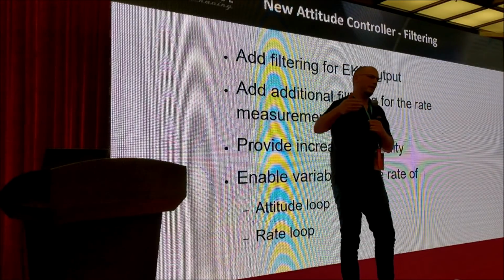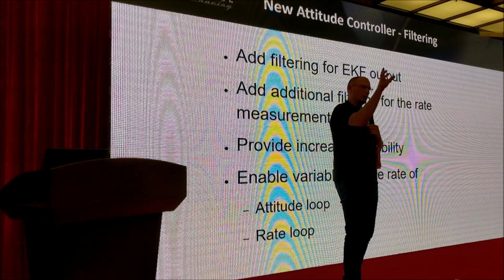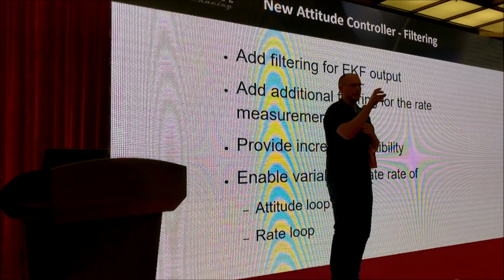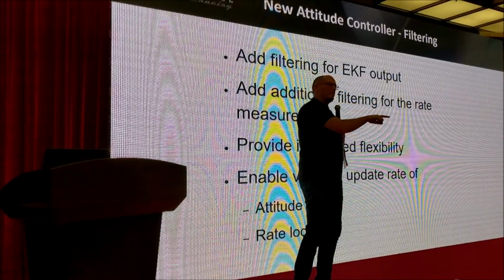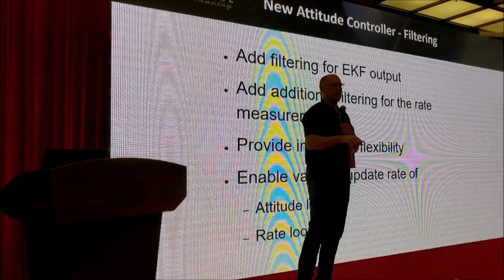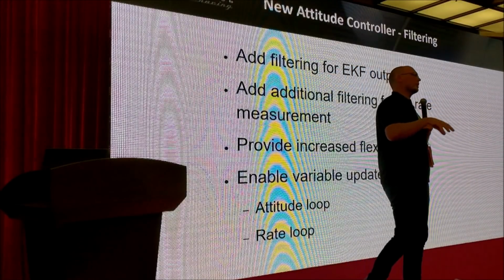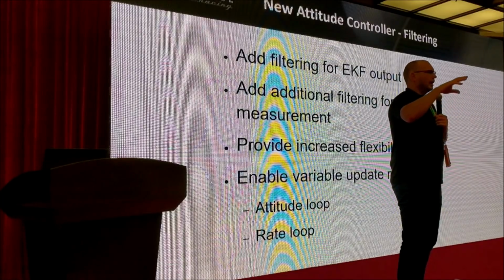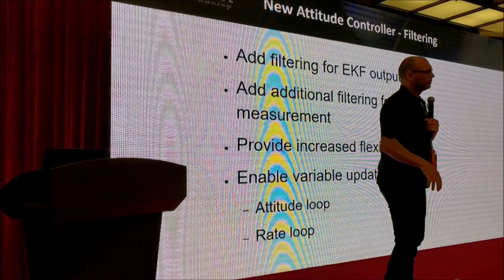By recording a flight, you're able to show that at this throttle level, you see a strong noise at this frequency. As you go up in throttle, it moves up to here. So by placing a notch filter that will cover that range, you're able to attenuate the strongest noise in the normal operating areas of your aircraft.